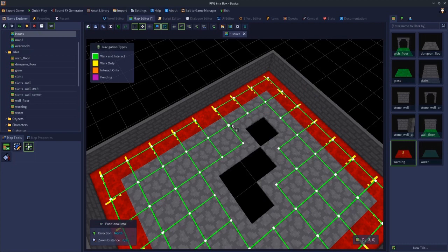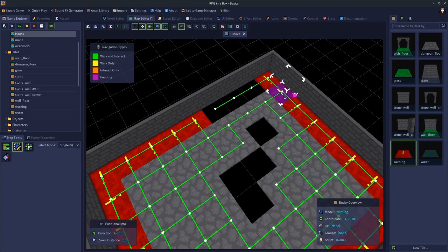So if we select the floor tile and delete it, those lines are staying because they're not actually on the floor, they're on the wall. Okay, this line got deleted just a second ago, as will this line, this one going this way, because that was connected to that tile. But these ones going around, the ones I drew here, they're all actually on the wall.